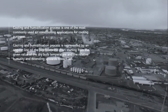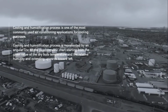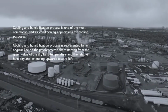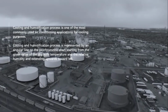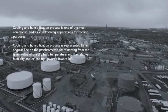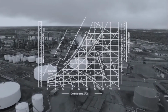Cooling and humidification process is one of the most commonly used air conditioning applications for cooling purposes. Cooling and humidification process is represented by an angular line on the psychrometric chart starting from the given value of the dry bulb temperature and the relative humidity and extending outward toward the left. So, here is the example of a psychrometric chart.